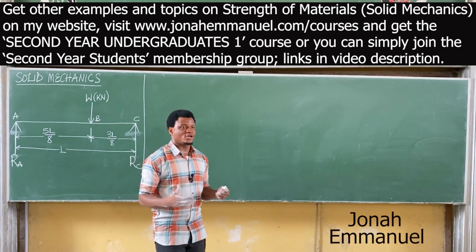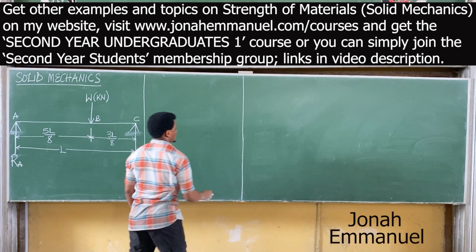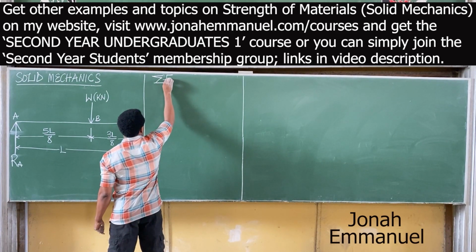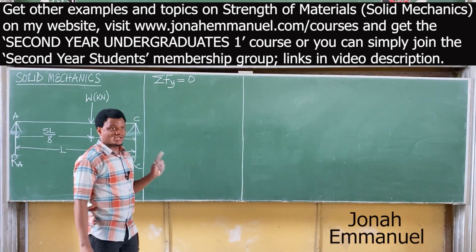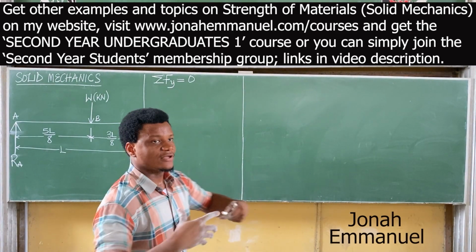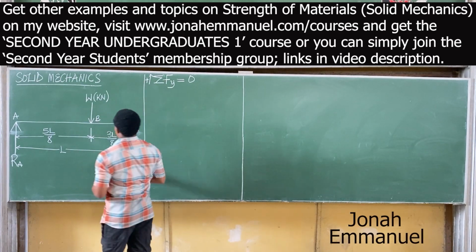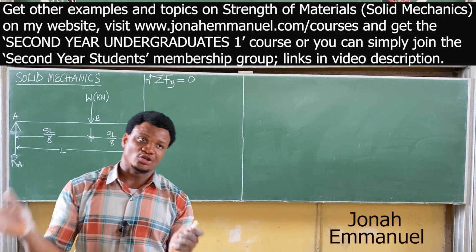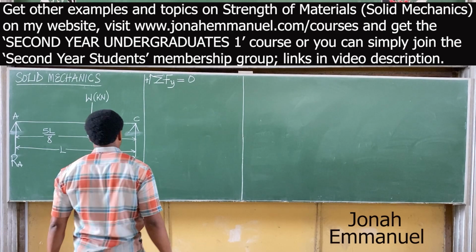Number two, we'll bring out the equation of static equilibrium, which says that the summation of vertical forces equal to 0. Sigma F vertical equal to 0. And I said for this one here, I am choosing to say all upward forces should be positive. Some lecturers will prefer to reverse it. They will say downward should be positive. If you do that way still, we'll get the same answer at the ending. So nothing spoiled. Upward forces should be positive.